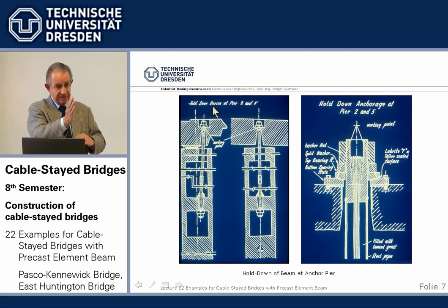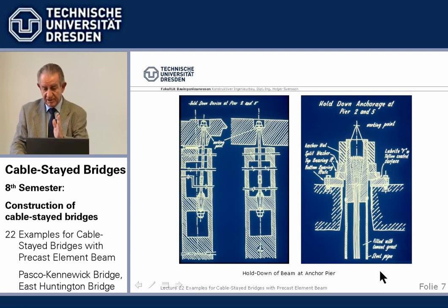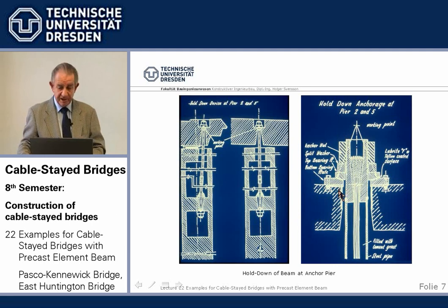So we must prevent a kink in the cable, and therefore we have used stiff steel pipes here, and we have placed the bearing on a sliding surface, so it's forced by the strong steel pipes and the sliding here that we always have a rectangle between the hold-down and the anchor head, and there is no sharp kink which could cause breaking.